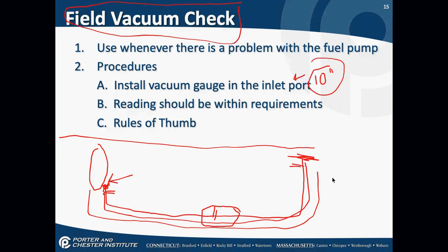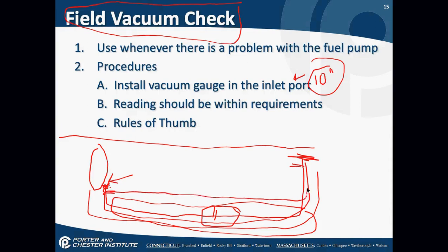Had he run a vacuum check and documented it on the service ticket that it didn't hold a vacuum and it didn't pass a vacuum test, and therefore there's a leak between point A and point B, and we cannot check what's under the floor, so we have to run a new oil line above the floor over to the burner, that technician and that company would not have been liable.